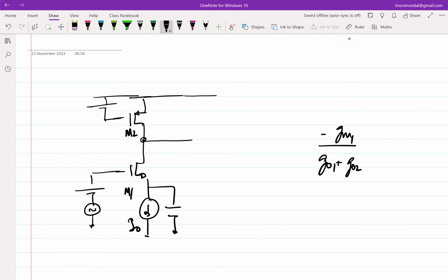As it turns out, if you keep on reducing current, then the transistors will eventually go into sub-threshold, provided you have biased it properly, and then this GM over GDS ratio kind of remains constant. So as long as the transistor remains in saturation, you can get some leverage by decreasing I naught. That's fine, but still you'll get limited by GDS, because ultimately it's not as if you can push I naught to 0 and get infinite gain. That's not going to happen.